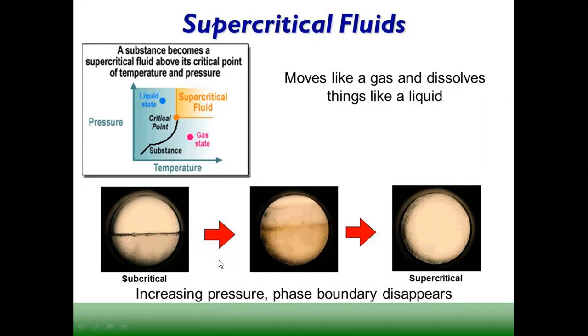If you increase the pressure, regardless of the temperature, the phase boundary line is going to be destroyed in order to convert the subcritical fluid to a supercritical fluid. The fluid in this state has viscosity, density, and diffusion coefficient always intermediate to liquids and gases. Therefore, supercritical fluids become highly advantageous for separation processes, either by extraction or chromatographic techniques.